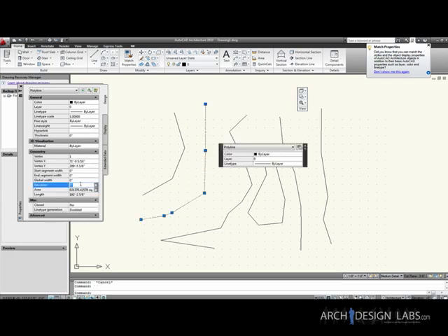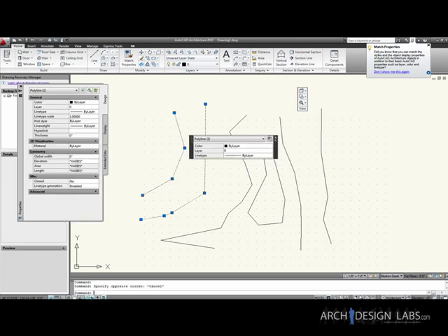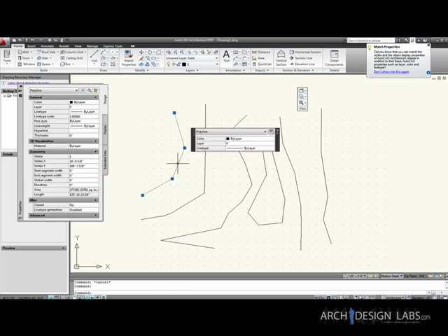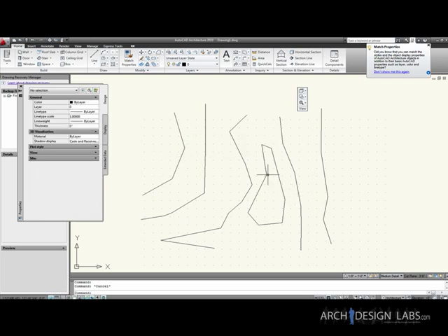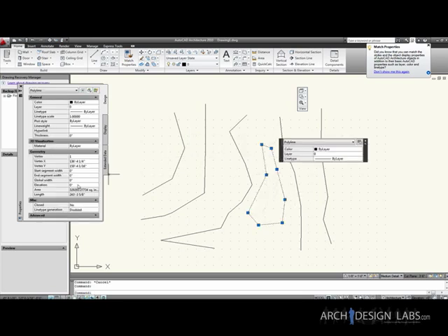This could get repetitive if you have a million lines, but it's still faster than drawing the lines yourself using a point system, which would be nice if Revit just allowed you to simply choose the lines, but it doesn't let you do that right now. So the quickest way is to come into CAD and adjust the elevation on each of these lines.